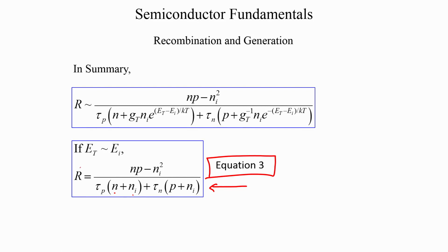and it is something that is extremely useful in making a quick computation. So, what this expression tells you is it gives you a gauge on the recombination rate, that is the rate at which the electrons and holes are being annihilated, okay, in non-equilibrium. Okay. So, n and p are non-equilibrium values. We have taken the semiconductor out of equilibrium. What is the rate at which the n and p are being annihilated or are recombining? So, that is what R is.